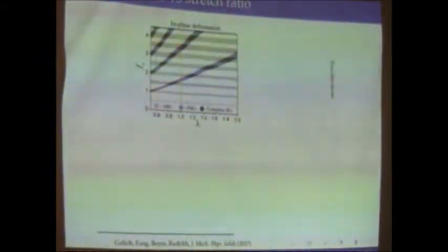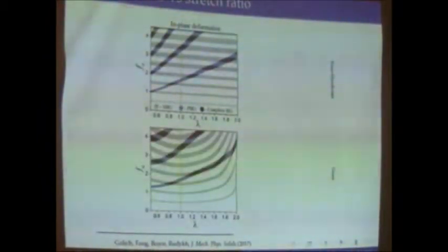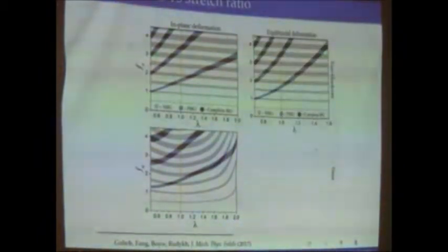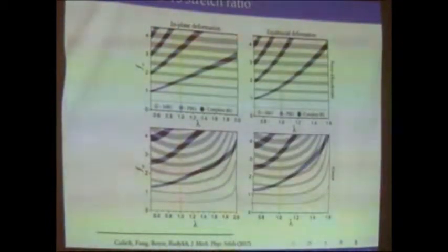On this slide I just want to show that this is for in-plane deformation, when we don't allow deformation in the third direction. And I want to show that it's not really related to the type of deformations that we apply, in 2D and 3D. There is no limitation for that. So indeed, Gent material will produce changes in the shear wave band gaps, but for now, this is equibiaxial, so a 3D type of deformation, and you also can see that shear band gaps stay the same, but pressure band gaps change a lot.